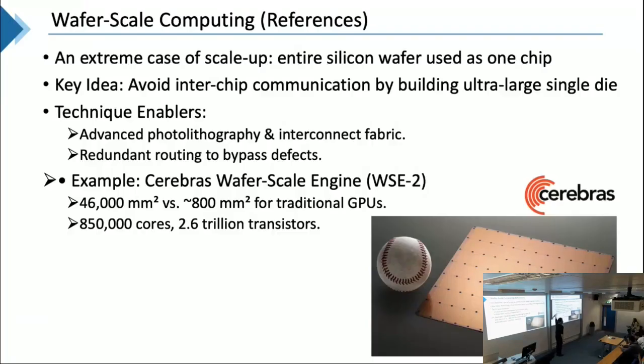So this is the traditional GPU manufacturing process. You divide this large wafer into small chip areas. The reason behind this is that the larger the chip area is, the more likely you will have a defective chip. So that's why most of the mature chip manufacturing uses a small chip area. They want to improve their yield rate. Yield rate reflects how many defective chips you produce by, let's say, producing